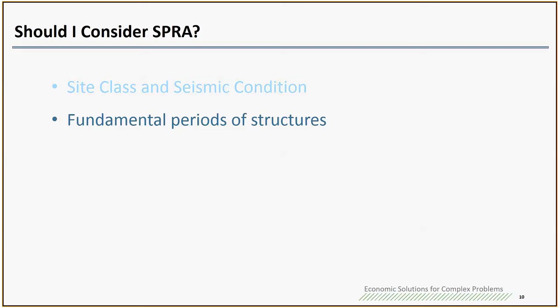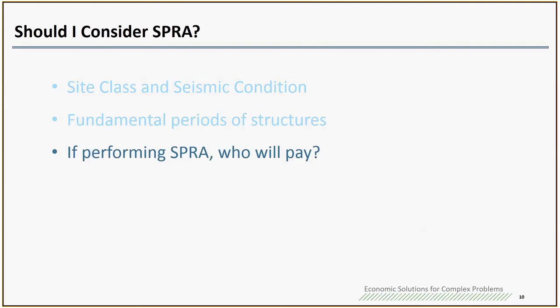So my recommendation is, if you have a site class E located in a moderate seismic area, with S1 greater than or equal to 0.2, always do the site-specific response analysis. Certainly, you need to consider who will pay, or whether the owner is willing to pay for this additional analysis.